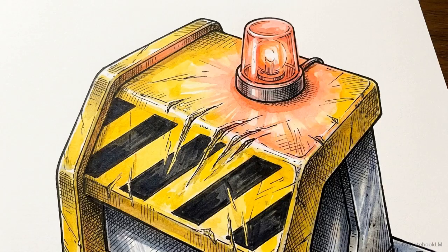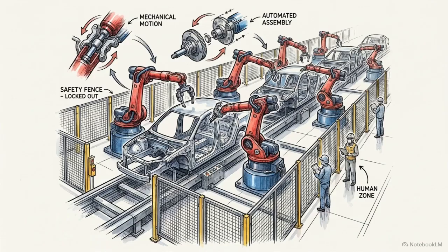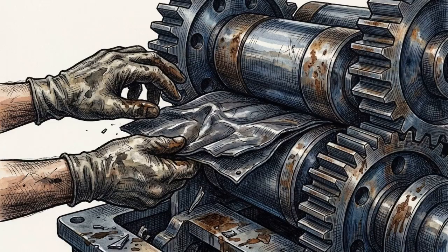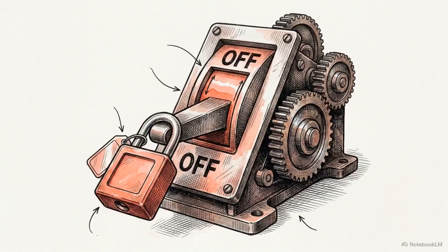Yet, physical guards and light curtains share one critical limitation. They are only designed to protect operators during normal, highly predictable production cycles. The most catastrophic industrial accidents rarely occur during routine work. They happen during maintenance, adjustments, or when clearing a material jam. Bypassing normal safety systems for maintenance requires an entirely different operational protocol, achieving a zero mechanical state.